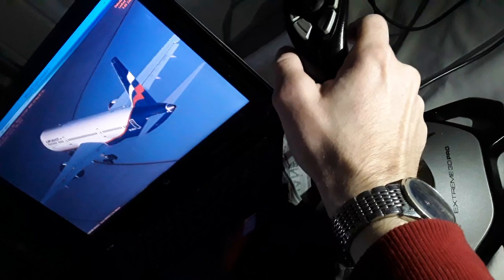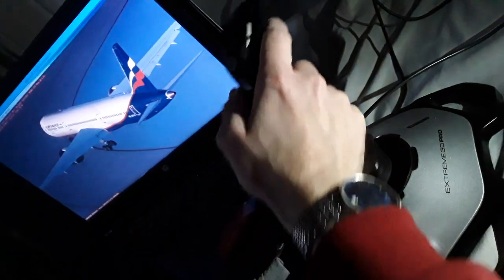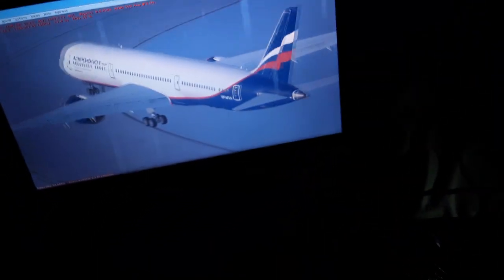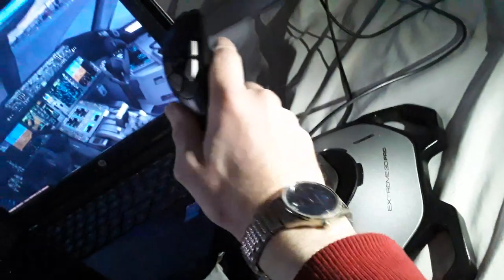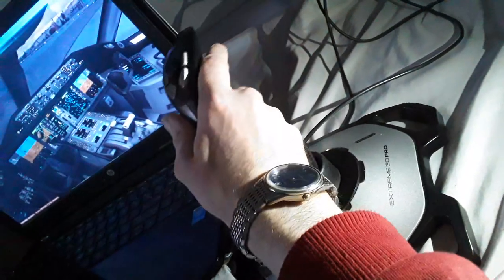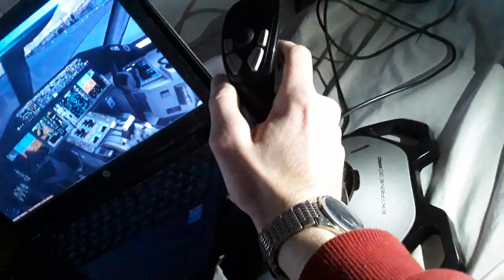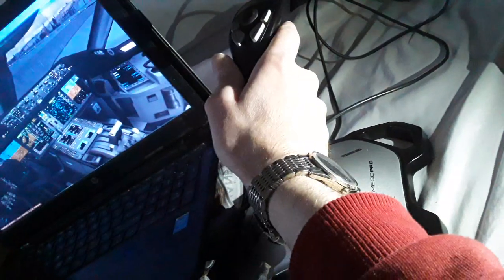Functions, so we make turns left and right, ailerons, elevator, climb, descent. This is side stick deflection proportional to the yoke deflection. In the Boeing we need to override one side. They move together, they're interconnected flight controls, both sides, the captain and the first officer. Now in the Airbus you have the side stick priority over here, so we go for the rest.